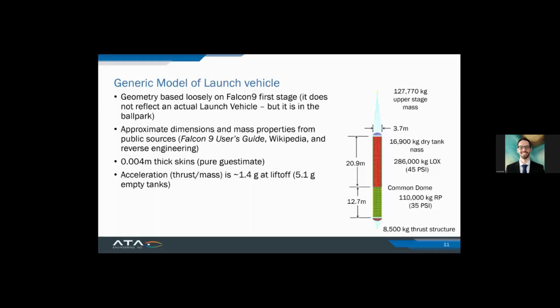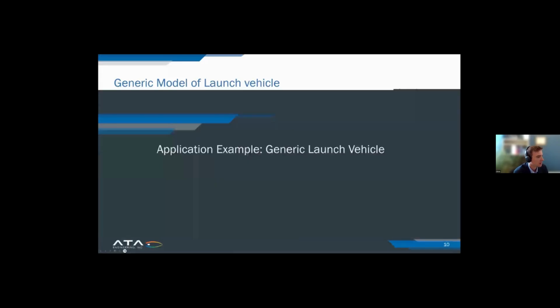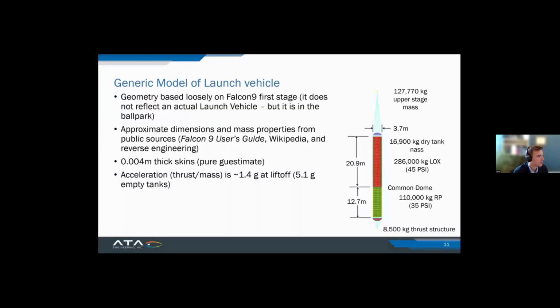Okay, continuing here, we have a question from Nino. Handful of questions here. First question is, how many elements should the fluid be modeled with in the radial direction? So I guess another meshing related question. Yeah, true. I think I would suggest 5 at least. That's what I've always had decent results with.